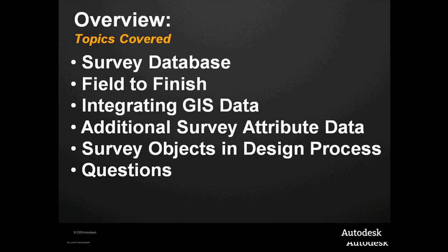There is a concept within Civil 3D, I don't know if you're using it now, but we can extend the survey point database or the point definitions themselves. Traditionally, a point has only had a point number, northing, easting, elevation, and a description. And we have the ability in Civil 3D that we can extend that to include additional columns of data quite easily.